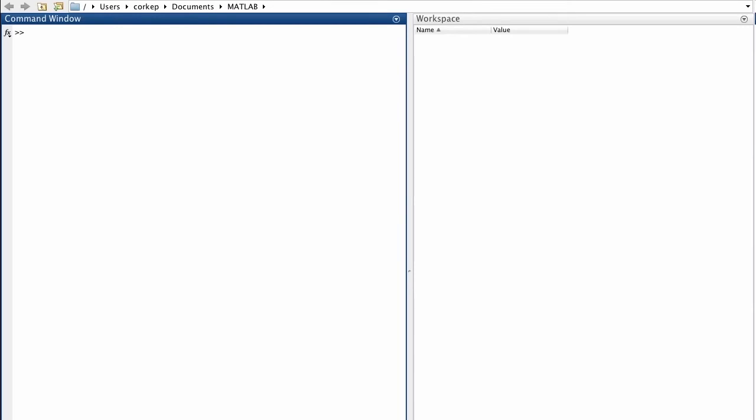Let's look at doing this in MATLAB. I'm going to define a couple of workspace variables, A1, which represents the length of the first link, and Q1, which represents the joint angle. Now in order to determine the end effector pose, I need to multiply together a couple of elementary transformations. And an easy way to do this using the robotics toolbox is with the function called trchain2. It computes the result of a chain of homogeneous transformations.